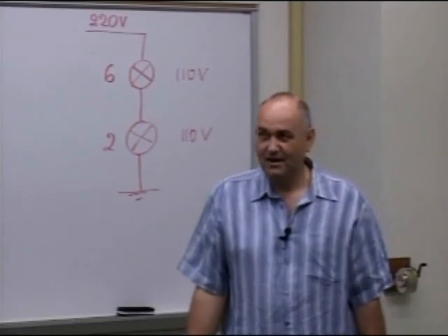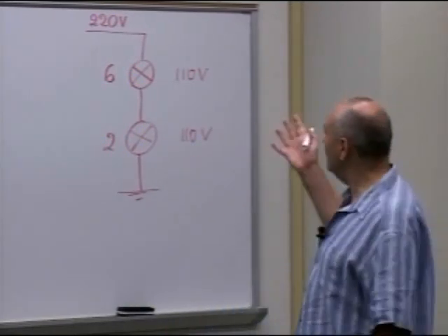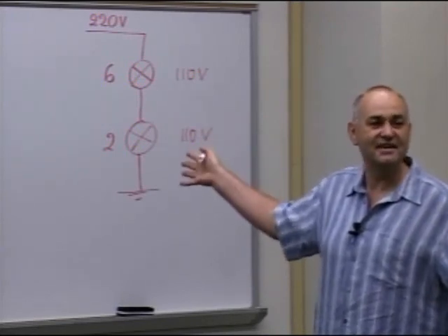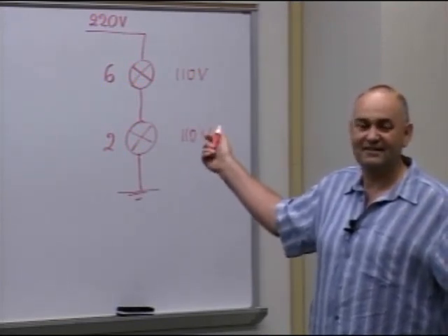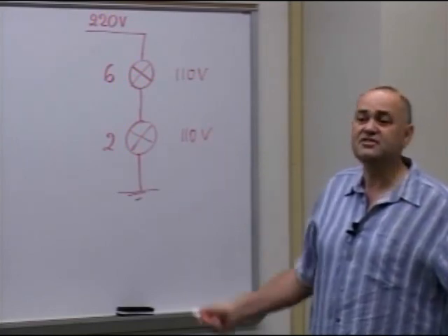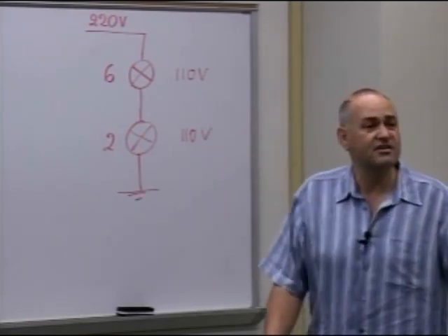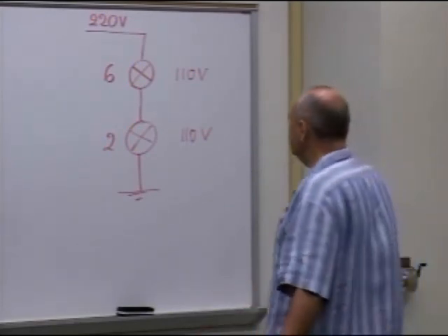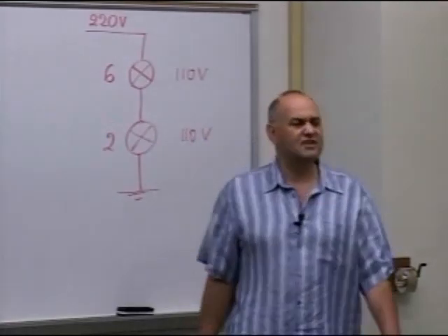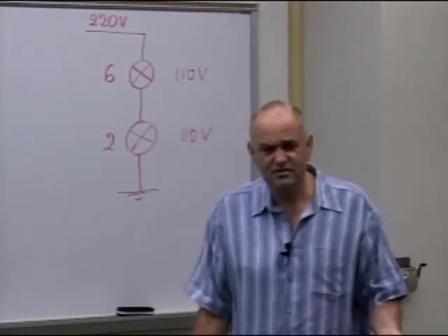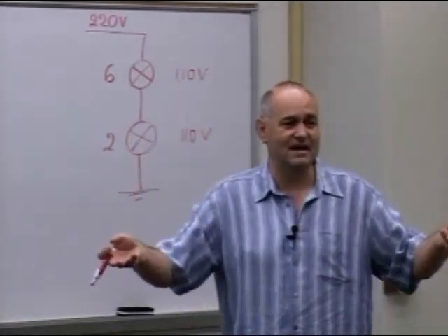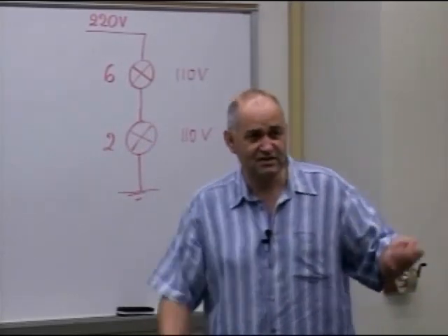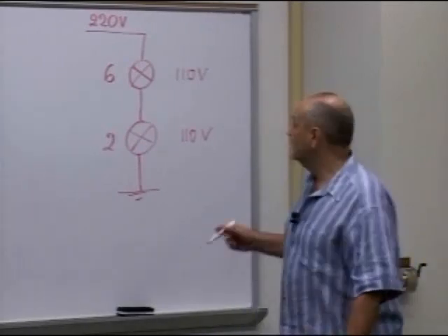Over here you have, what do we have? It is a configuration which we discussed today. Series resistors, correct, but it is a voltage divider, right? I forgot to say that. I assume that you assumed it right away, that I take two identical light bulbs. Because if I had a 40 watt light bulb and a 100, then one of them would burn.